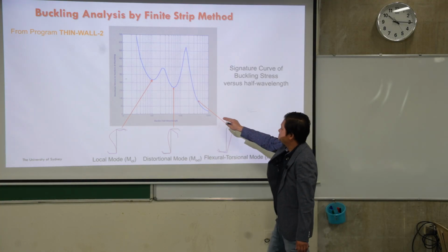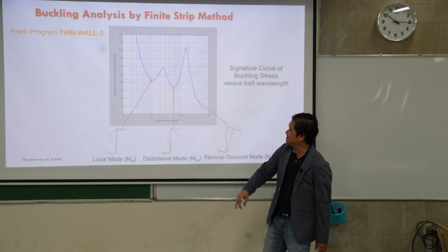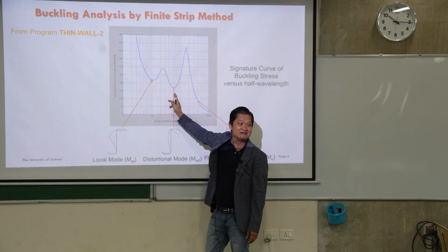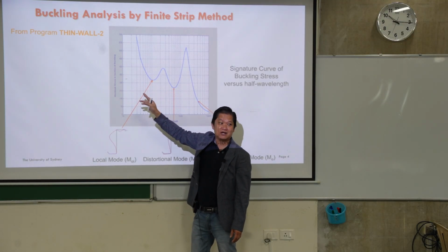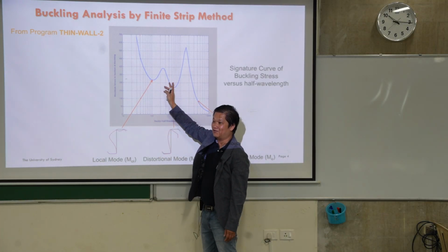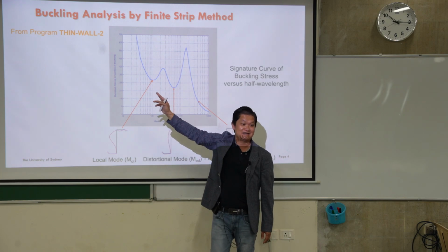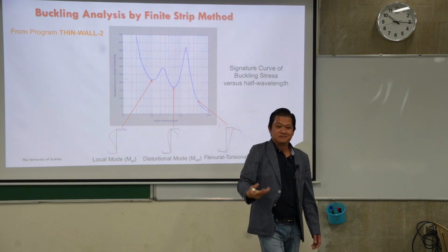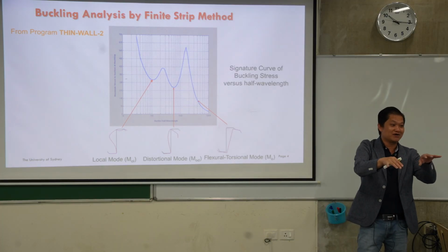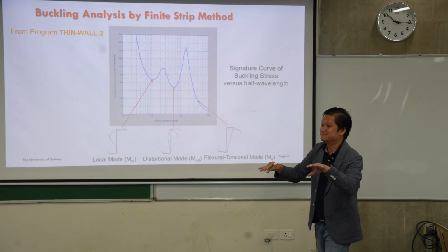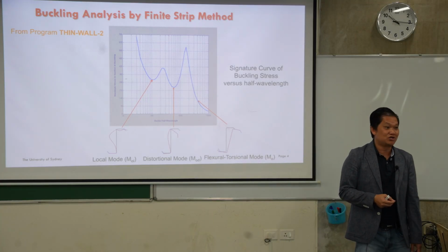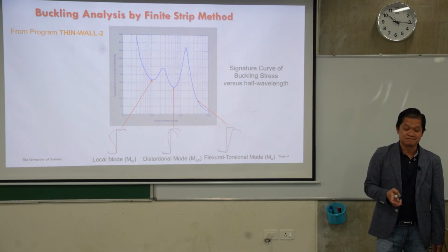Yes, so now, as an engineer, we don't want to design something very good in local buckling, but bad in distortional buckling, right? We don't want to design some beam that is going to fail right here, but is very thick or good in section capacity. So, for optimization, as an engineer, we need to make sure that those three are very similar. That is the best one. That is the maximum or optimized solution for any type of structure.